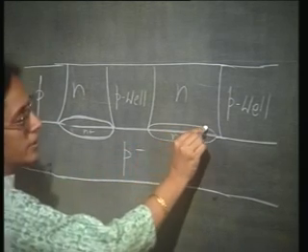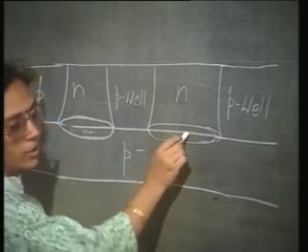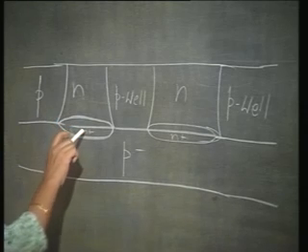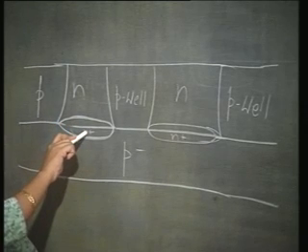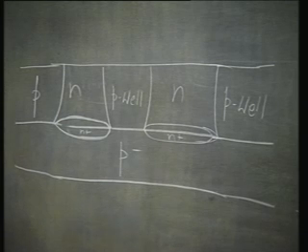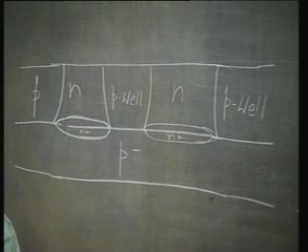I have the buried layer which is going to cut down the collector resistance for the bipolar junction transistor, and this buried layer is going to cut down the substrate resistance to suppress or prevent the latch up problem. Okay.